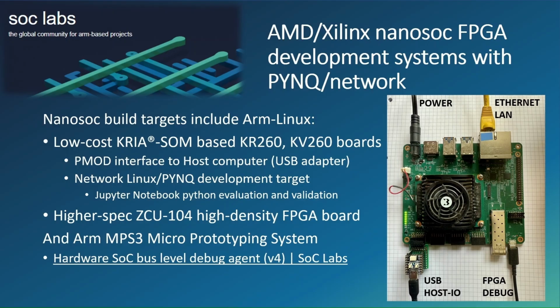For the FPGA deployment, we've targeted a few boards so far. So we've got the Kria SOM boards, which is then for testing this external I/O interface. We've got the PMOD to a Raspberry Pi. You've obviously got the PYNQ interface with these boards and with the ZTU104, which allows nice, easy Python code scripting for the validation. We've also taken one of the ARM MPS3 boards for then a bare metal implementation. So really kind of trying to mimic in FPGA what we will have in silicon.